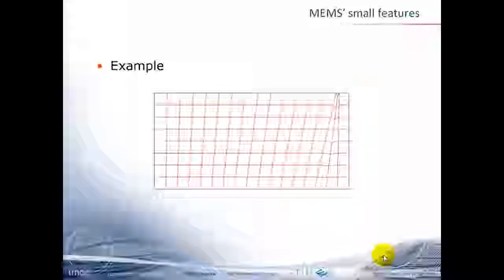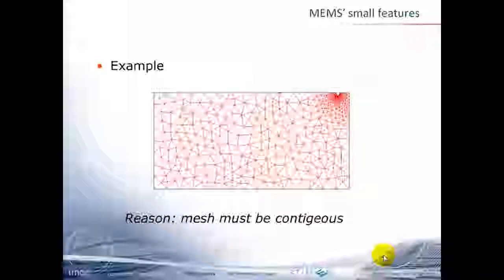Go back to here. I can, let's say, have a node here, and of course in the assembly matrix there should be the same solution for the node here belonging to that element. The solution should fit with the node from that element and that element. I cannot have a node that just ends in between. That is not a problem for triangular elements, because you can always reduce or increase the number of divisions on the side.